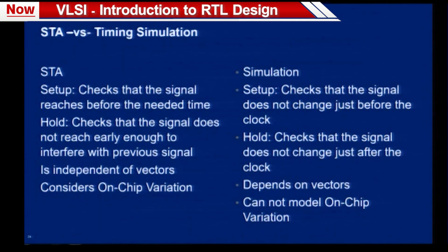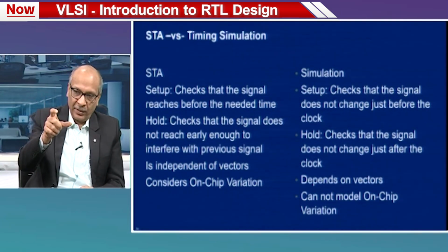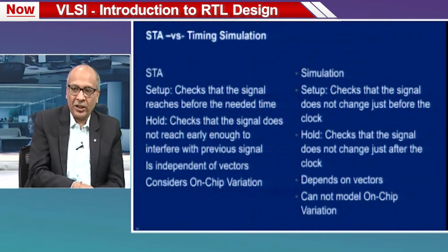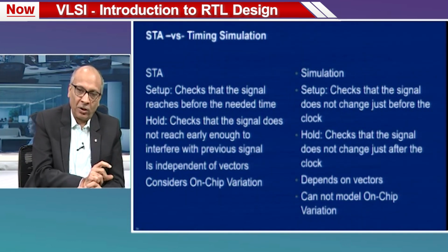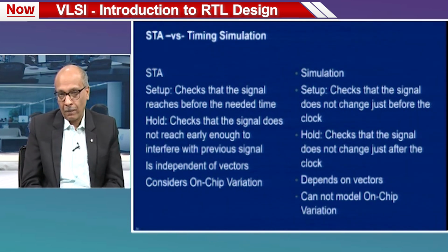So, let us look at the little bit difference on STA versus timing simulation. Most of you have read about setup and hold in your books, and the definition of setup and hold in your books is similar to what we have defined under the simulation category. Setup checks that the signal should not change just before the clock. For certain duration before the clock, the signal should not change. That is the definition of setup as you have read in your book, and that is the definition that simulation uses.